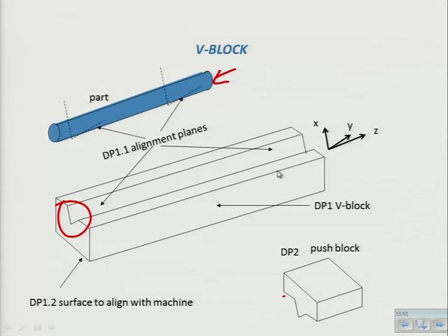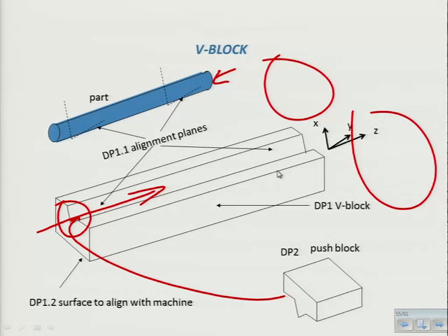So I set this thing down and take the push block, push it up there, and then I can push it down that way, and then it engages the wheels down here. When I push it in, it goes through and gets drawn into the gap between the wheels and ends up doing a nice centerless grind on that part.